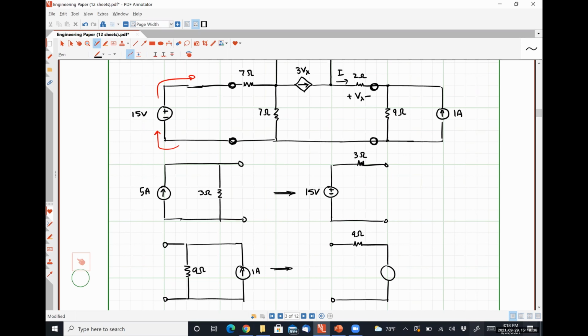No. If I put the 3 ohm on the bottom, like I talked about a moment ago, there's nothing wrong with that, but it's not as obvious that you can combine that resistance with the 4 ohm resistor to give you the 7. So as long as you're doing everything appropriately, you can change the order of your elements to make your connections easier to understand, right?